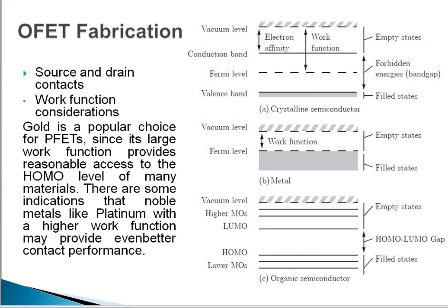By engineering the electron energy level of the organic semiconductor, it is possible to set the HOMO and the LUMO levels so that the equilibrium potential at no bias sits in a region which is thermodynamically stable against redox reactions. For p-type material, experiments have shown that the HOMO needs to lie more than 5.2 volts below the vacuum level.